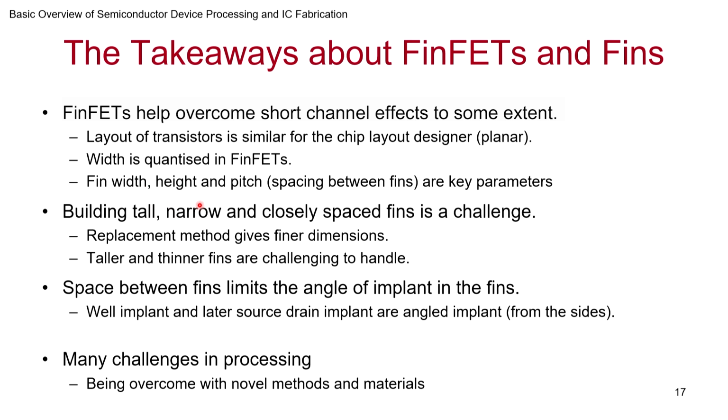The fin width, height, and pitch are the key parameters for the fin. They end up defining to some extent the W of the transistor and the size of the transistor. The L of the transistor, of course, is defined by patterning the gate poly on the fin. You need to build tall, narrow, and closely packed fins as much as possible, but it's a challenge. As we saw, the replacement method gives finer dimensions. You use the mandrel, and around the mandrel you build a spacer, and using that you could get taller and thinner fins.